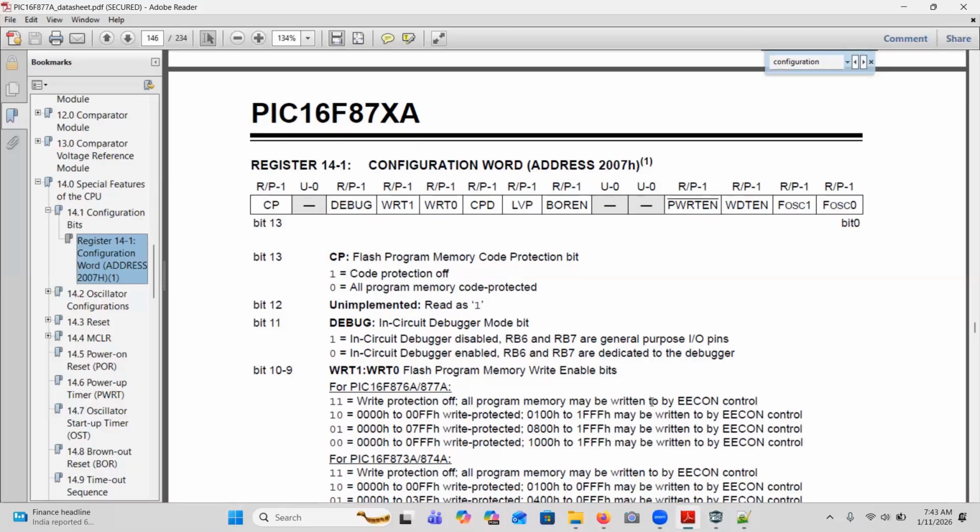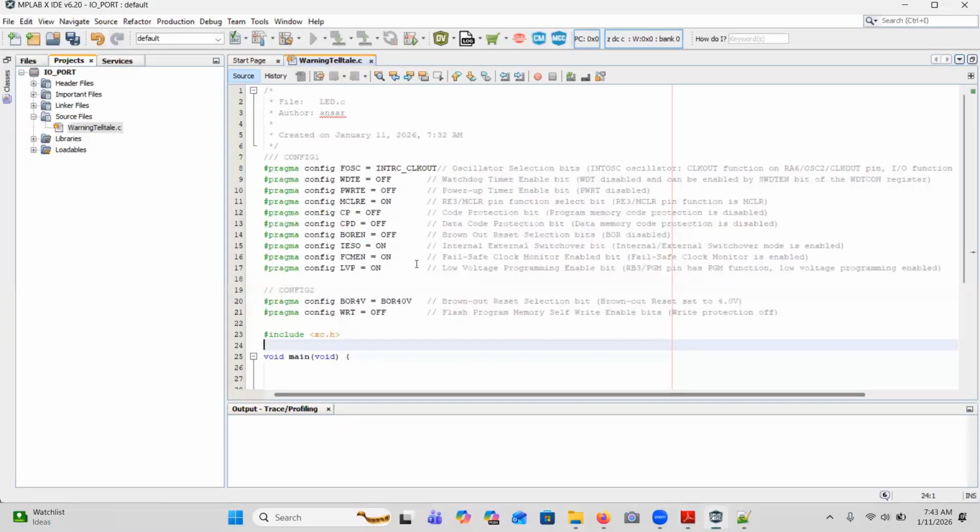So you have to do that via this pragma directive. That means before you build your binary, you will make these settings. Only after that will you go for building the binary. This is because the pragma is a preprocessor directive. So before they create the binary itself, we have to be ready with these settings.